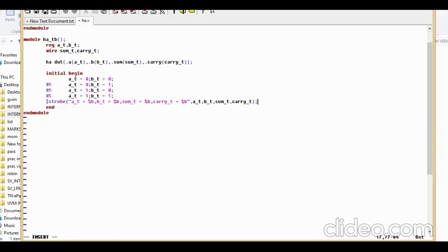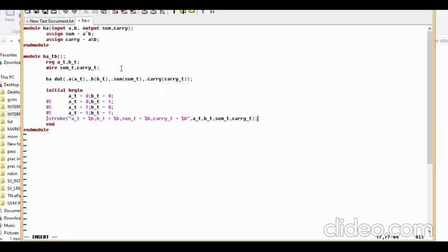Okay, so this is known as your linear test bench, only this much. The three things: the instantiation, being clear with your data types, then passing the possible values, and then having some display statements.